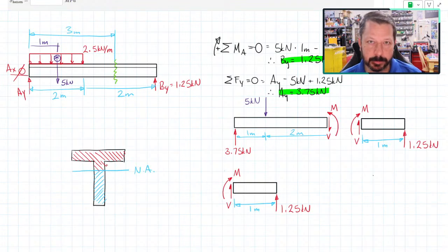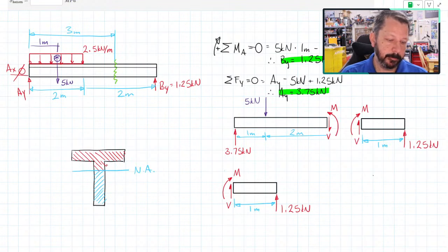Most of the time the beams are bending downwards, but you could have beams that have loads pushing up on them. So that's one reason it matters, because it could be tension or compression. And most materials don't care about that until you get into civil engineering and these beams are concrete, and concrete behaves very differently in tension versus compression. So then it really matters. But for ductile metals, like what we're going to deal with in this class, it doesn't really matter as far